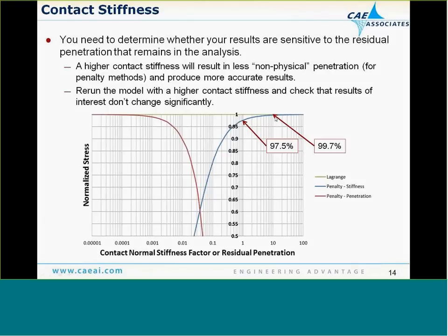So you can see here just taking the default from 1 to 10, bumping up the stiffness an order of magnitude, maybe that's what we're looking for in our error. And it just shows, again, that you can't always rely on all the defaults in Ansys to give you the accurate answer that you're looking for. It's your job to try to understand what's driving the stress and reduce this thing that's an artifact of the penalty method.